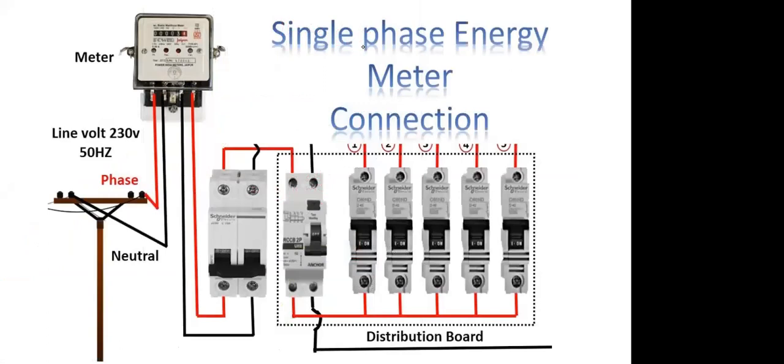So this is again a similar diagram to what we discussed in the theory class. You can see again the neutral. Actually, this should be the neutral wire, the black cable, and the red one is the live wire. It passes through the electric meter, but here they have not put the fuse. After that you get the main switch, then the RCCB. All these components are available in your house.